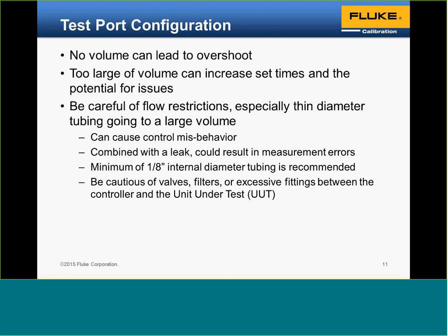It's very important to look at how you have the test port configured and how you have items connected to the test port. If you just plug the back of the test port, if you put no volume on it whatsoever, perhaps just testing out the performance of the instrument, you just received the instrument, you just want to play around with it, but you're not actually calibrating anything yet, that can lead to overshoot.